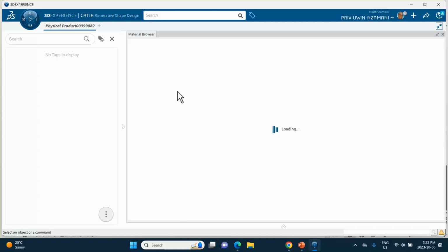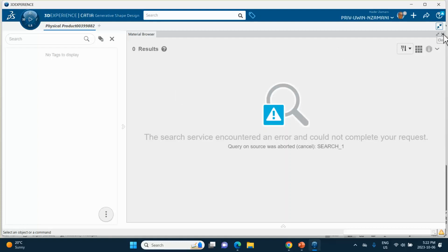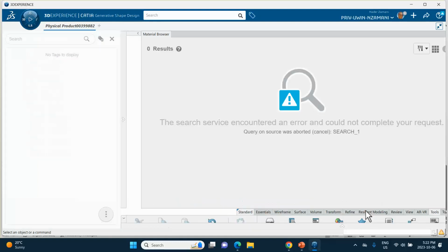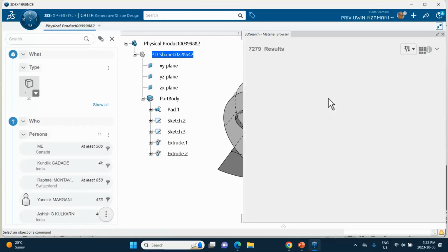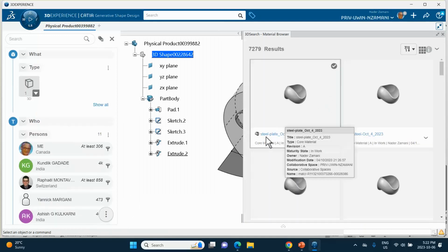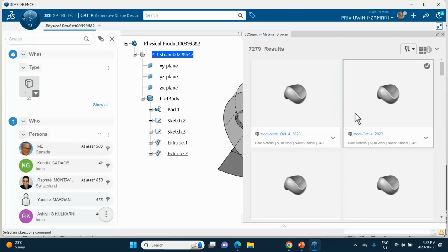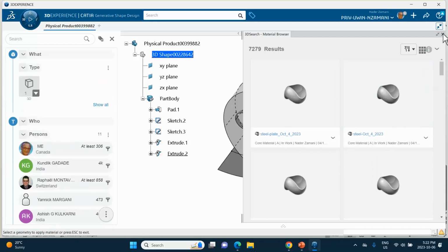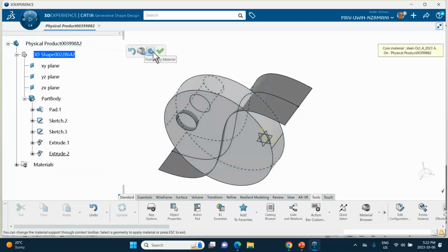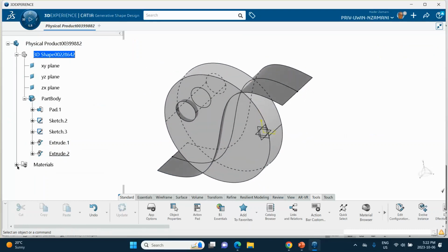It was probably easier if I just inputted those things. Oops. Let's try it again. Material Browser. Okay. So here is steel plate. Okay. So I'll just use steel. Apply. What we do is not needing material, but since at the very end I want to do an FEA run, I apply material to that. Okay, it's elastic properties of steel. Let me just make sure.